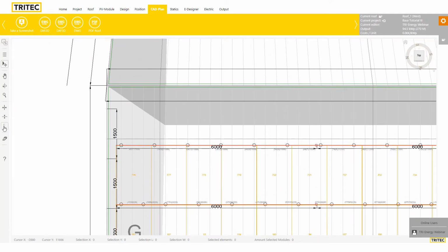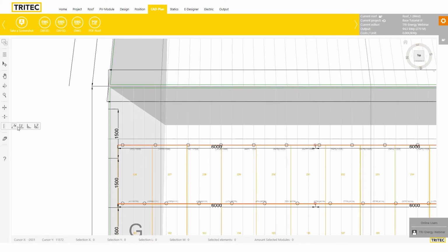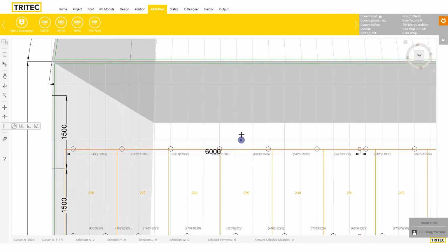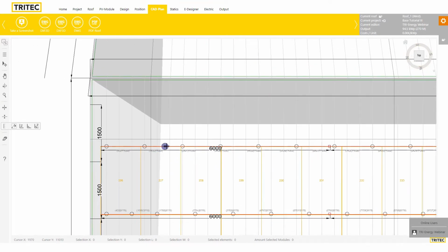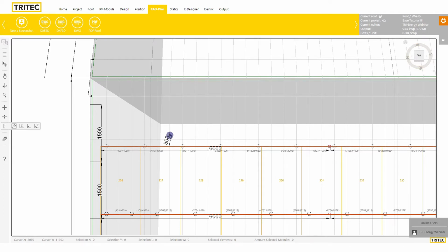And you have this tool here. Once you click that, you have again a flyout indicator set, meaning that you could measure into the height. Maybe you would like to have some measurements if there's some interference area, some chimney, for example, you would like to have from the roof surface to the top of the chimney. Very rare case. Standard, that's this tool, so totally free. And you see there's also a snapping mechanism, and maybe you say, well, I would like to have from the end of the rail on top to the ridge of the roof.